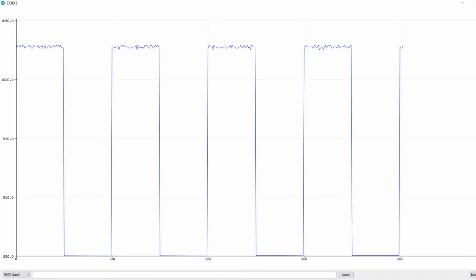A digital signal represents a series of discrete values. In an Arduino, it is limited to two values it can alternate between. One of them being ground or 0 and the other the supply voltage, 5 volts. These two states are also called low and high. In practice, the signal won't be perfect and noise and distortions will be present.